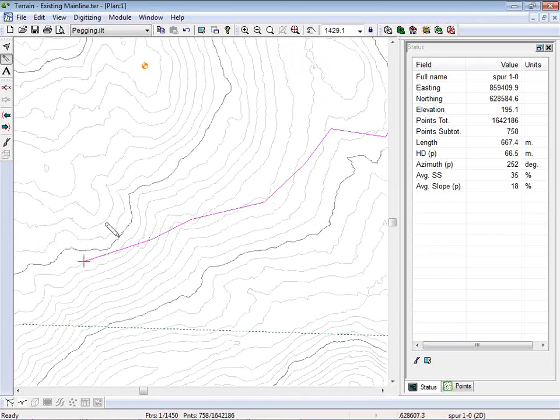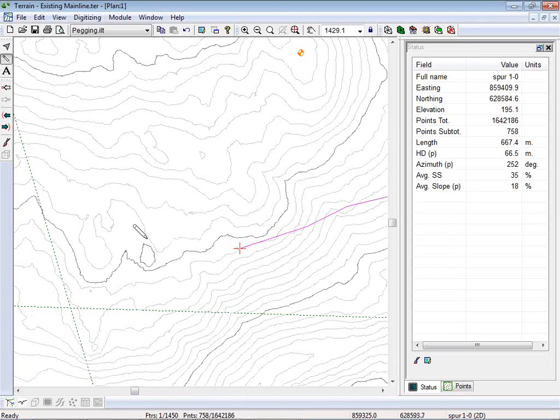This is going to be full bench cut probably because my side slope is pretty steep. It's not hugely steep, but it's pretty steep. Now we're getting into the switchback area. There we go, 10%. Let's do a switchback here. So that distance there is 43. In other words, if I made a switchback that shape, it would be 20 meters radius. Okay, sounds reasonable. Let's do it about like that.